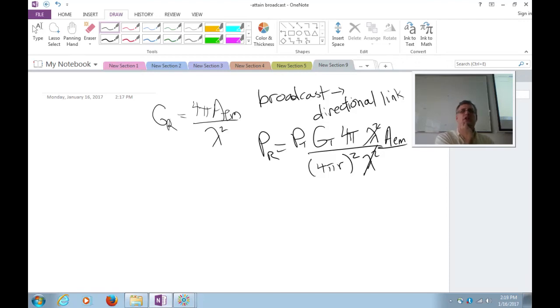It's a trick question. There is no frequency dependence. That is, if I am only concerned about exchanging electromagnetic energy between 2 points in space, if I have a fixed amount of aperture and I have the freedom to point it somewhere, it doesn't matter what frequency I use.